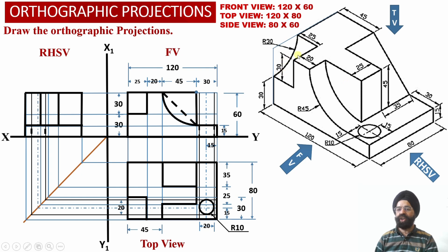And finally, corresponding to this circular cut section, which happens to be parallel with respect to the left hand side face, or perpendicular to the front face of the solid, we are going to obtain true shape projections corresponding to the circular surface with respect to this point over here. So this will be the point of the radius over here.